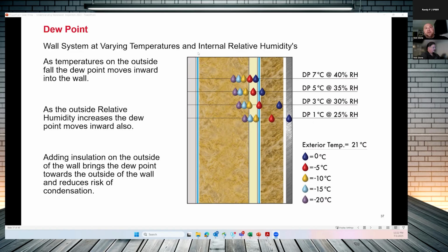Another thing to think about when it comes to wood frame is the cellular structure of wood. Is it the same today as it was building 20, 30, 40 years ago? Well, the answer is no. We're not necessarily building with old growth lumber, and now it's all fast growth lumber, so it's more susceptible to moisture. We're using more OSB than plywood, or even further back, we used to use wood boards on the outside, which can manage moisture much better.